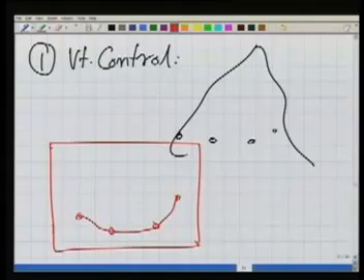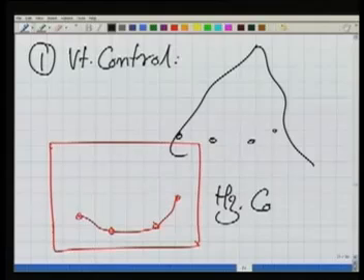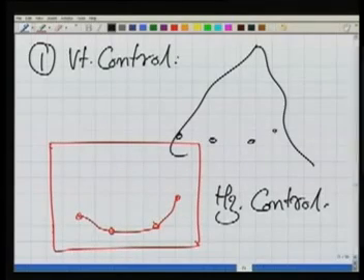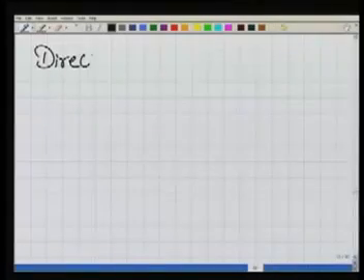So the next thing that I will have to do, I will have to go for horizontal control. So in any contouring job, we will have these two basic things to be done. We locate the points, vertical control. Yes, these are the points at same elevation. Then we plot these points on a sheet and join them. So this is the horizontal control. Now how we actually do it? The very first method which we say is, we say this method as the direct method.